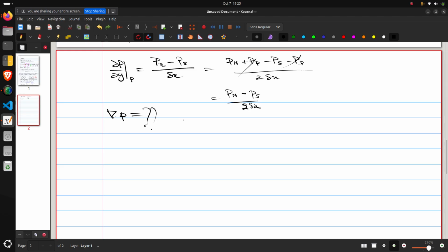So this idea came about that we evaluate variables like pressure, density and temperature at the nodes, at the cell centers, but calculate the velocities at the staggered grid, or at the faces. So what does it mean? Let me just draw a small schematic.